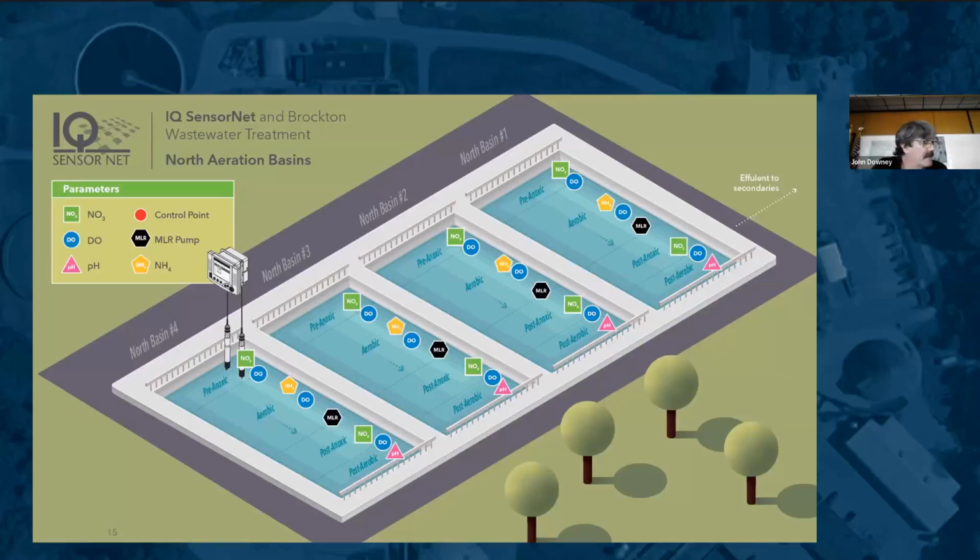Originally, these were located downstream of the midpoint dissolved oxygen sensors. They were in the vicinity of the recirculation pumps, which is the spot in theory after which we're not going to convert any more ammonia to nitrate. This is a very reasonable choice at the time it was made, given the process conditions.